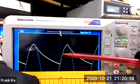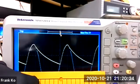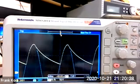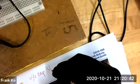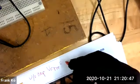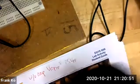So given this very first capacitor, I would write down the following information for mine, and you're going to write down whatever is appropriate for yours. On mine, without the cap, my V ripple peak to peak is approximately the full 25 volts peak to peak.